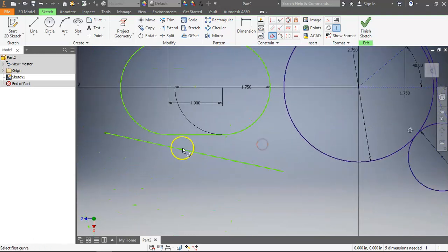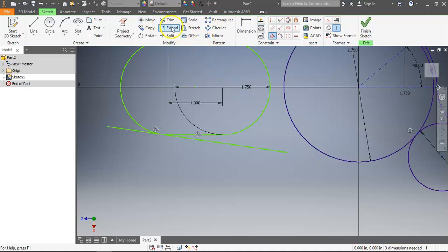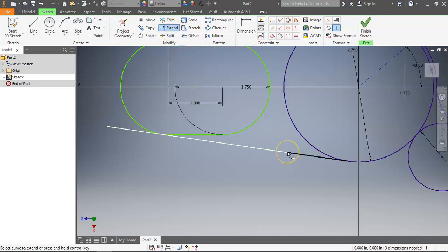And then this one, being only a line, it's actually no different. You're going to click line 1, line 2, and then line 1 and line... See, it won't even let me click this line, so it has to be this one. And now here's what I was saying before about making the line long enough. This doesn't connect to that line, right? So if you ever run into that case, you can do an extend. An extend will project it until it does hit the part.